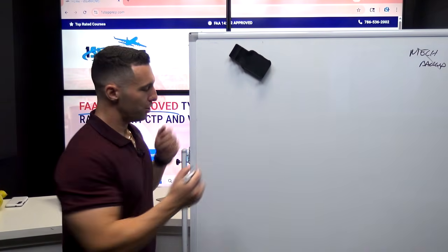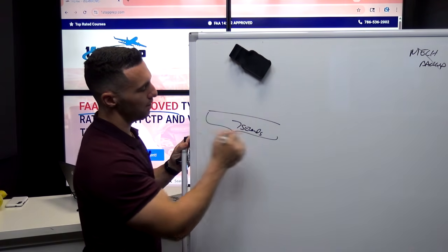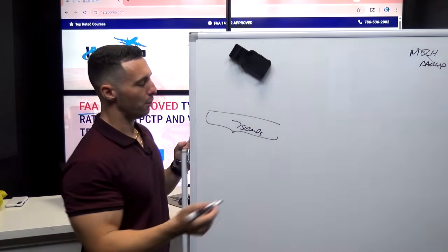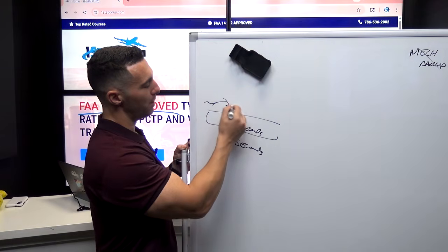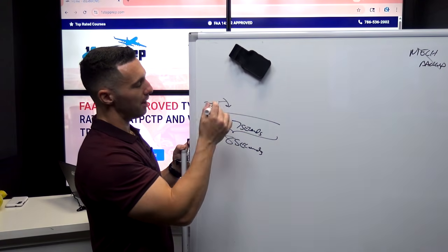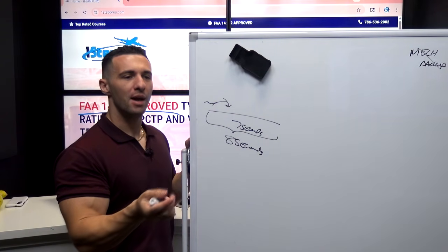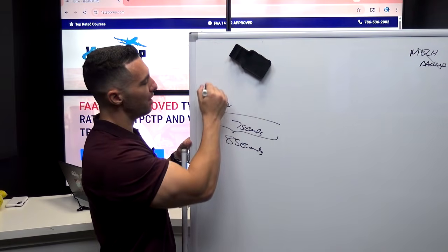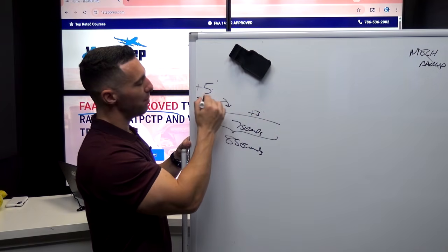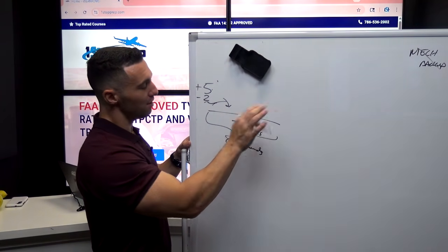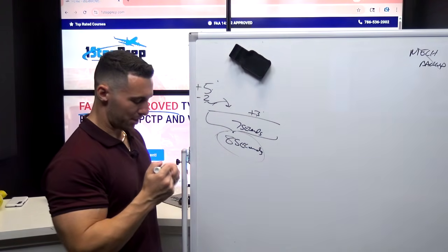And then your flare should take all of about 7 seconds, right? So the flare is about a 7-second thing. And that's relevant too because the flare mode, by the way, is active for 8 seconds, right? So at 30 feet, the nose down pitching moment happens, and it's taken that saved or stored pitch attitude and applying -2 degrees to it. So if your pitch attitude was +5 degrees, you're going to go down to +3 degrees, which is effectively 5 minus 2, right? It's going to take you to 3 degrees, and it's going to do that over a period of 8 seconds. And that's why your aft input is going to become a necessity for you to flare.